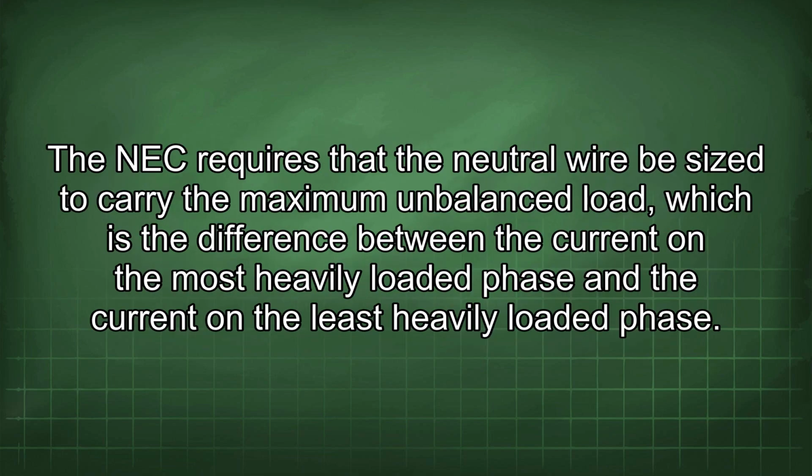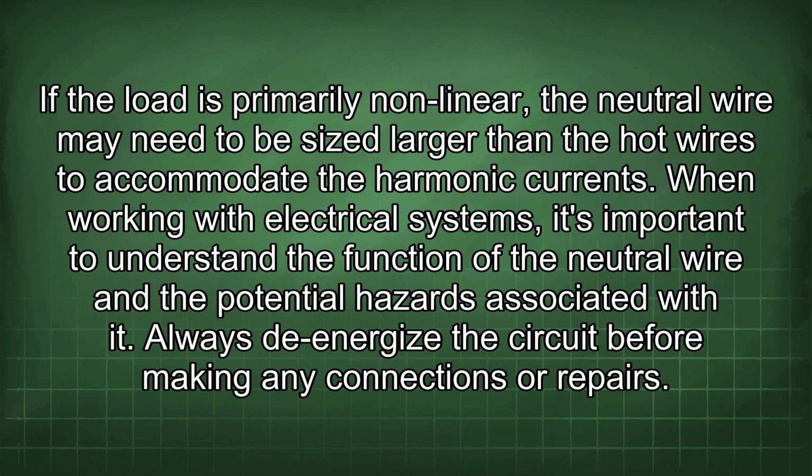The NEC requires that the neutral wire be sized to carry the maximum unbalanced load, which is the difference between the current in the most heavily loaded phase and the current on the least heavily loaded phase. If the load is primarily nonlinear, the neutral wire may need to be sized larger than the hot wires to accommodate the harmonic currents. When working with electrical systems, it's important to understand the function of the neutral wire and